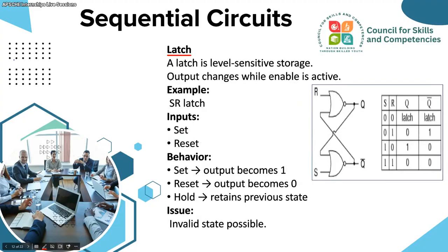Latch. So till now in the combinational circuit, we didn't talk about storing anything in the circuit. If we give an input, the output is there, that's it. But when there is no input, that output is gone. So somewhere we have to lock that output. Somewhere we want to go and latch that output. How do we do that? That is where the latch comes in.